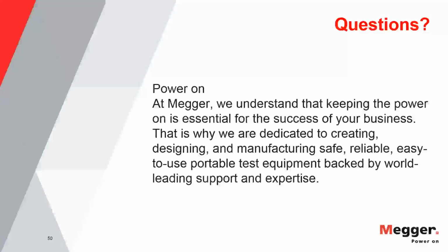So DAC is your go-to diagnostics wave shape, while the cosine rectangular is your go-to withstand wave shape. And what Jason also explained very nicely was that in IEEE 400, you have this combination test called a monitored withstand. To make this clear, this is a fully standard compliant VLF test, as you have to do it anyhow, but you use the partial discharge as a trend indicator. So the way you do the test is much different from a pure diagnostics test, as Jason explained, with these different steps where you try to determine the different parameters, specifically the inception voltage. You apply the voltage according to the withstand table, table 3 in IEEE 400.2, but you use the PD as a trending indicator to see if there is any condition going on.